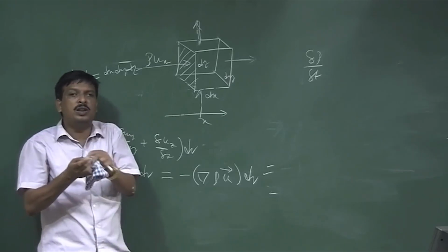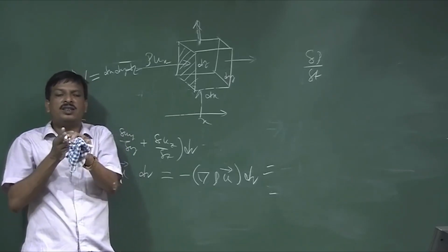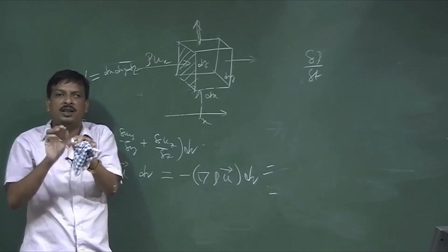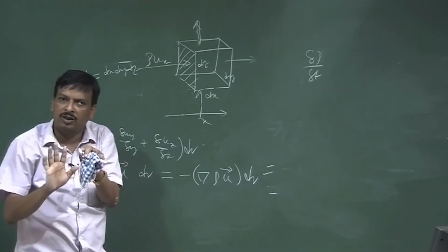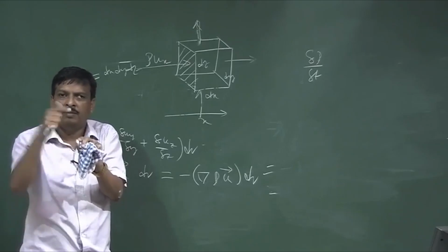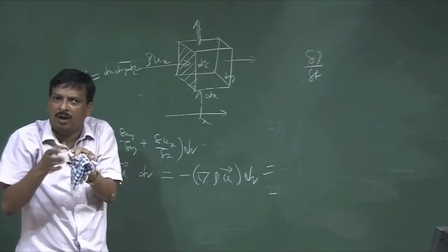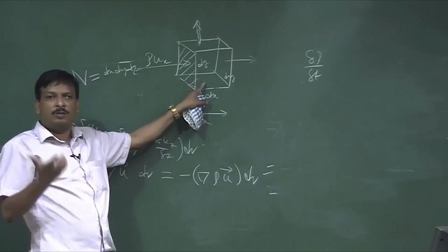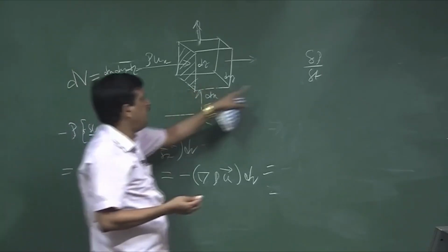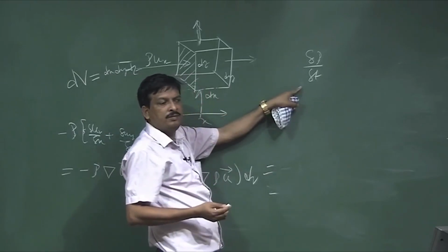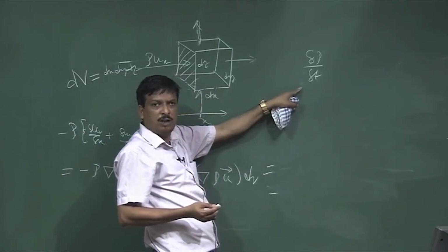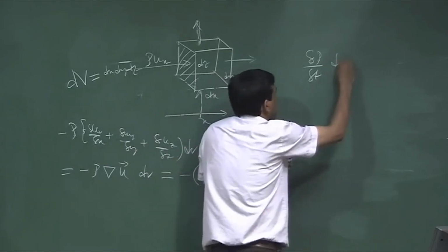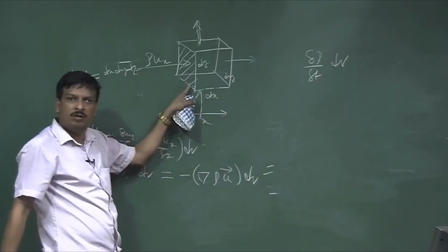Let us say initially it is 0. Once it started, mass flows into that side, and some mass will come out. So, net going in minus going out is the net amount of mass increase in that volume. In that case, that increases the density of the volume with respect to time. So, I can write del rho by del t is the density change with respect to time, into del V is the change of mass of that same volume.